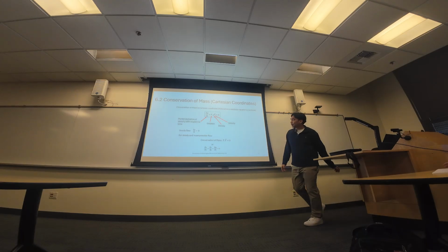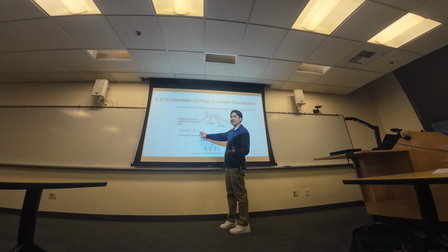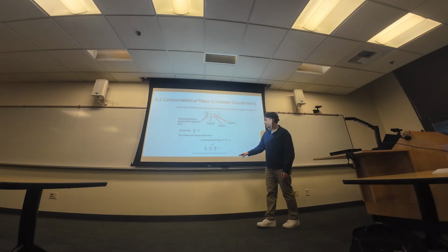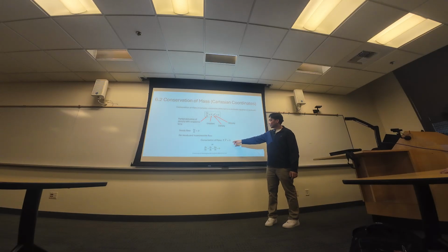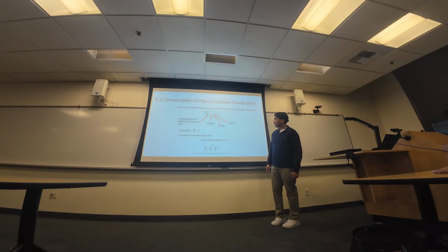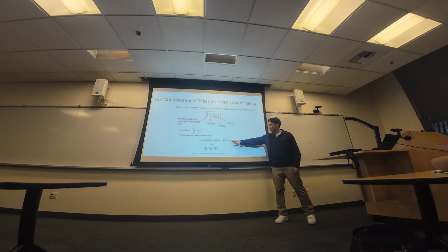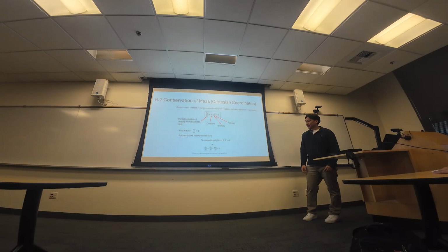Okay, for steady flow, which is a lot of the times we're doing, this is assumed to be 0. And if that is 0, you have your conservation of mass, nice and easier. It's just this: your del operator dotted with your velocity vector. And it looks like density is out because you can divide it onto the other side. And usually our fluid's not changing anyways.